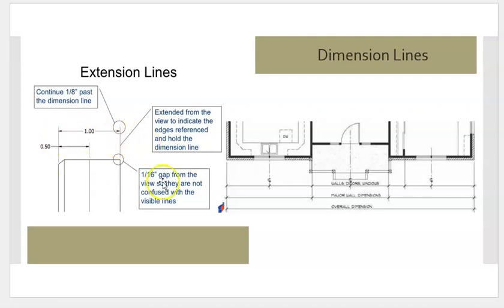So I'm reading the drawing, I'm reading the plan based on these simple basic lines. Over here on the right hand side with the dimension lines, you can see 3 different sets of lines going horizontally. And we can see in this floor plan that there's a couple jogs and windows and doors, right? So your outer line is always, always, always your overall dimension. What is the width of this house from left to right?